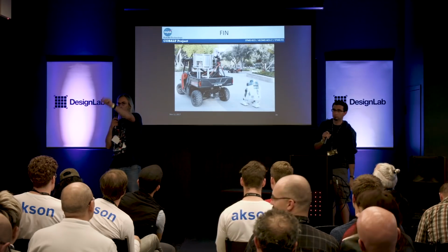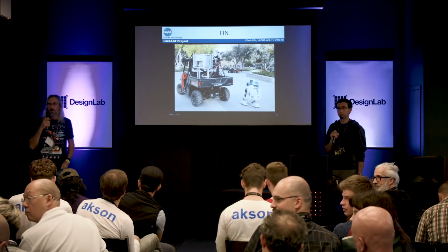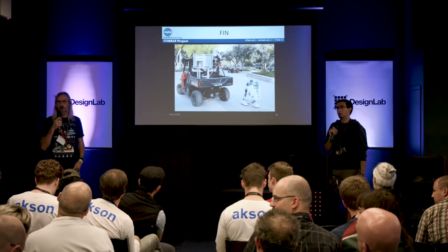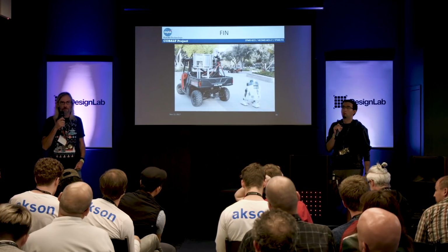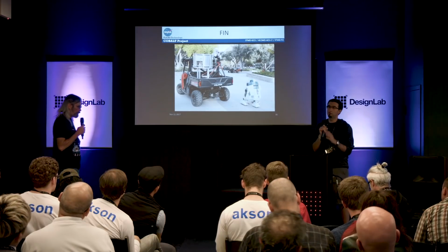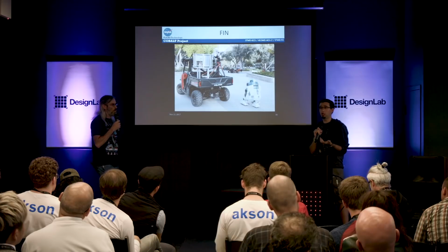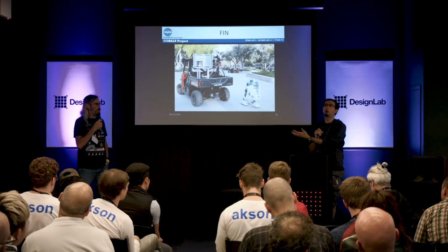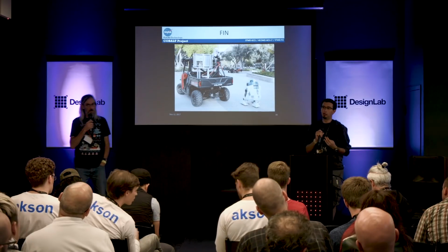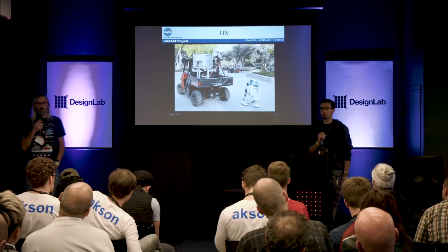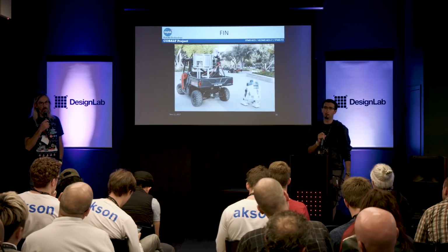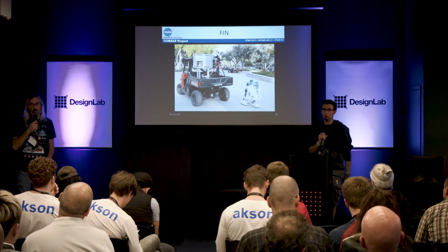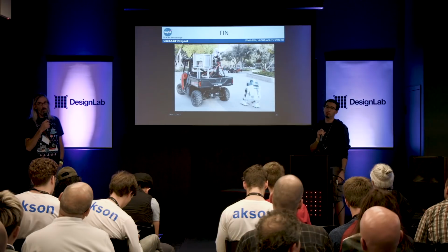One last question, back there in the blue. So as part of the miniaturization, is that going to be shifting to radiation-hardened target processors? You mentioned you have a Core i7 in there. What are you looking to replace those with? Right. So the i7 was mostly for housekeeping and configuring the FPGA and the Leon. The Leon has radiation-hardened copies of that chip available. We love using the RAD 750. That's a PowerPC processor that's radiation hardened. And in fact, the flight computer that Mars 2020 is going to have is going to be using an FPGA and a RAD 750.